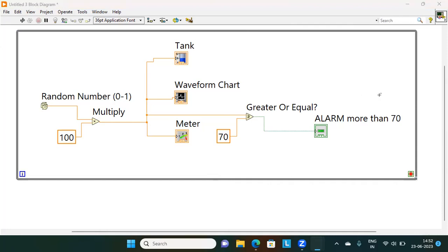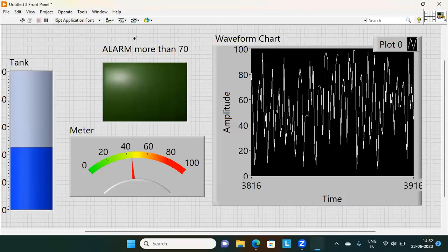Okay. Now see that when you observe the arrow button, now observe the run button. File is there, edit is there, and there is a run button. That run button is broken. Press Ctrl E, move to the front panel. You will find this run button is broken.